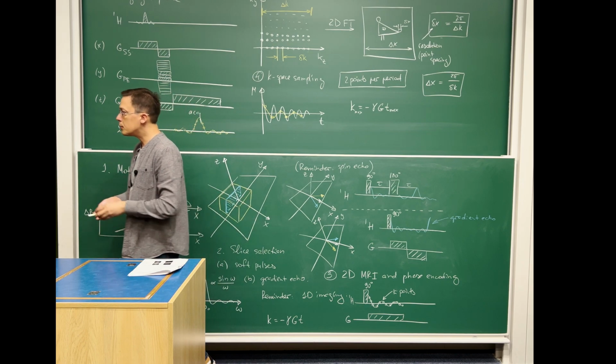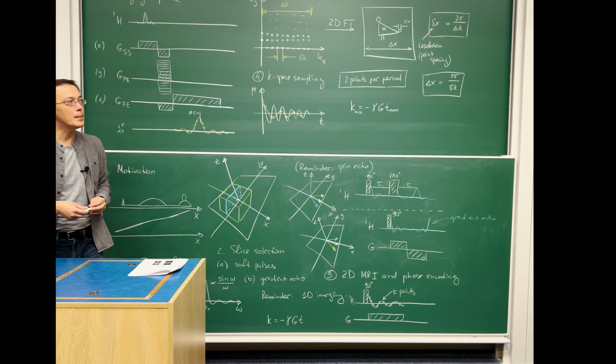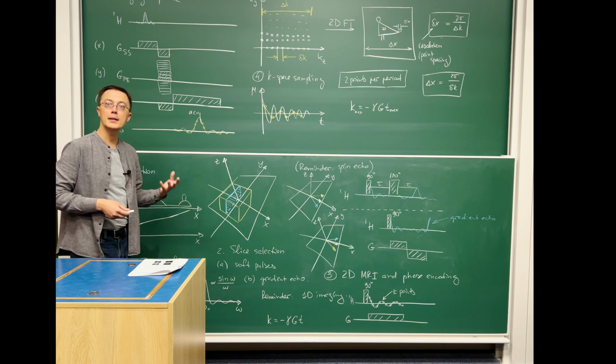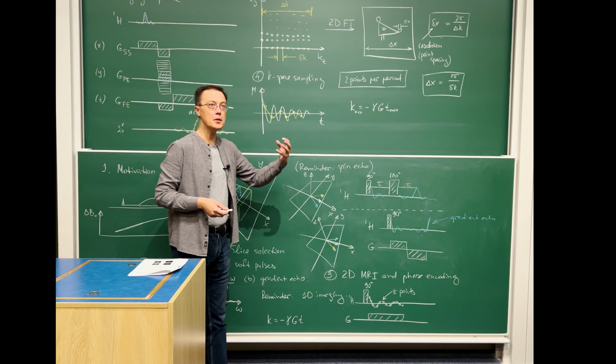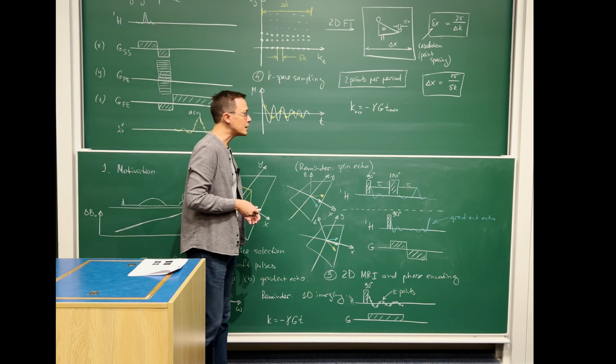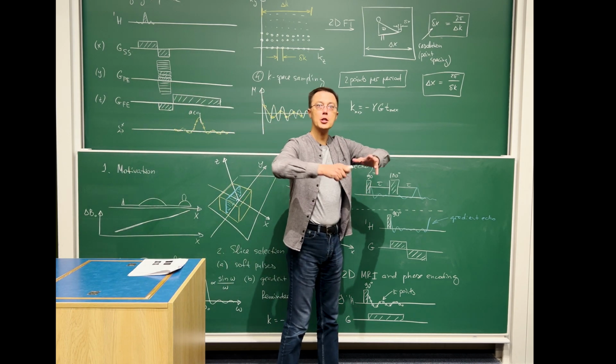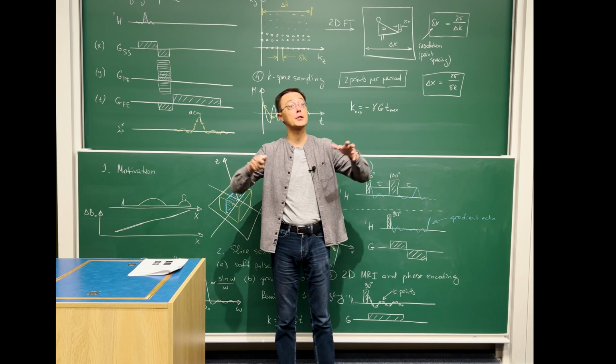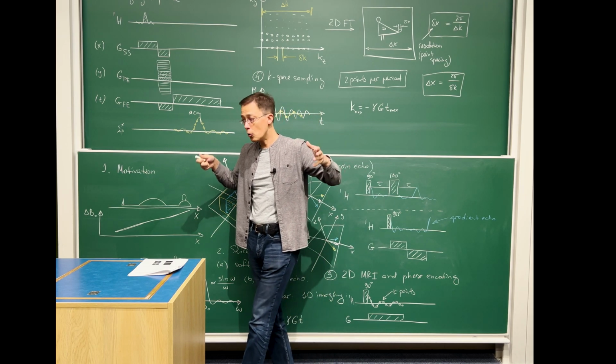But at that point you hit very physical limits. The derivative of the magnetic field appears in Maxwell's equations. The moment you have a rapidly varying magnetic field, outward pressure is exerted, mechanical pressure is exerted on the gradient coil.